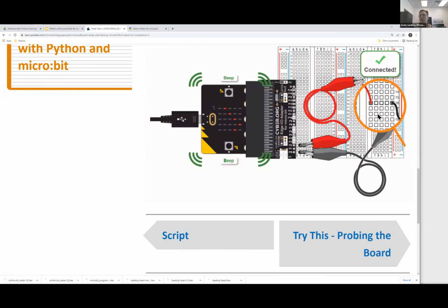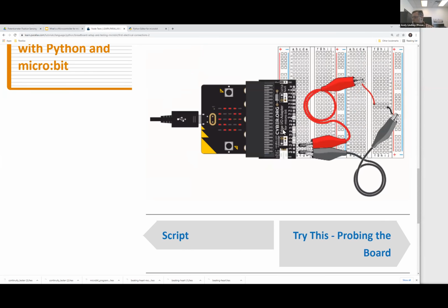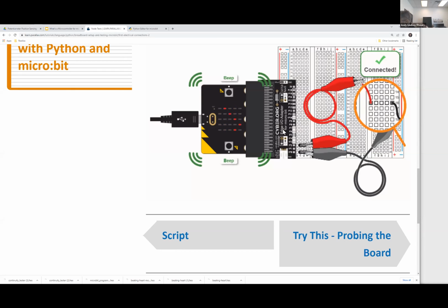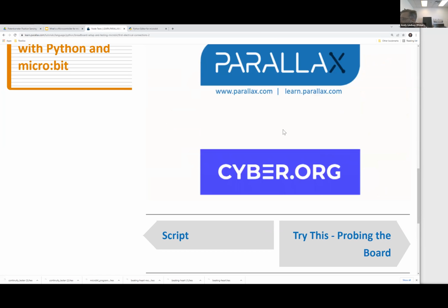And then once you've verified that you're in 16 and 17 with your wires and you see the no slash, try unplugging the black wire from 17 and then plug it into 16 and verify that you can see the check mark. Now it needs to sink well into 16. For some reason, I've got a wire with kind of a short end here.